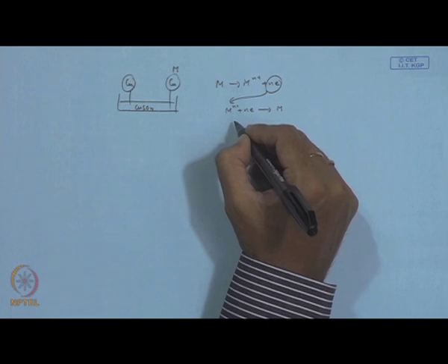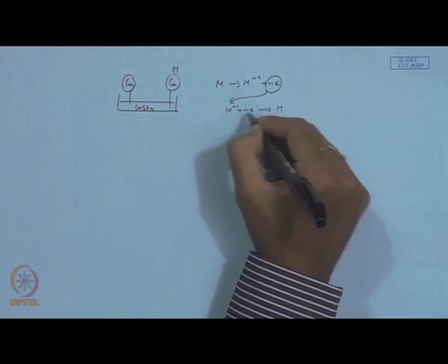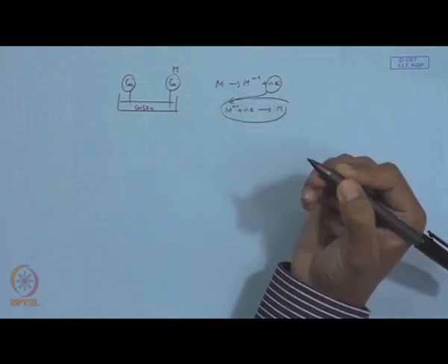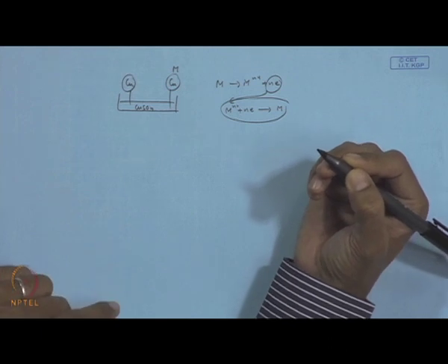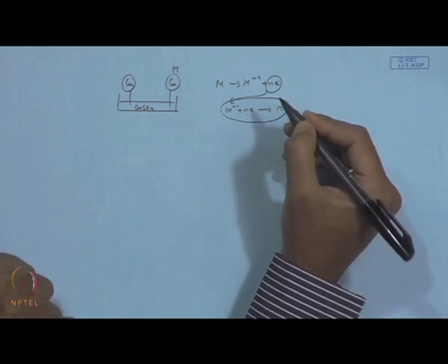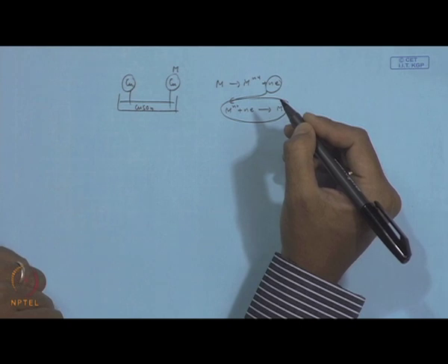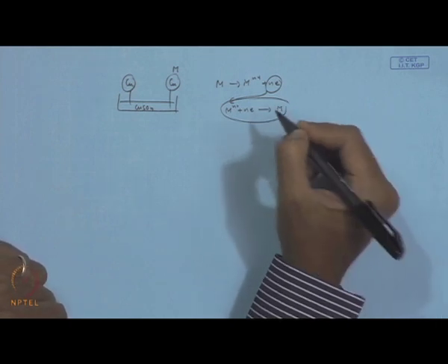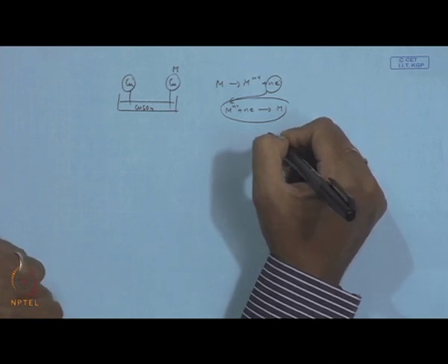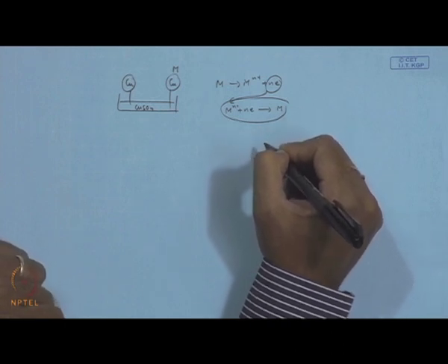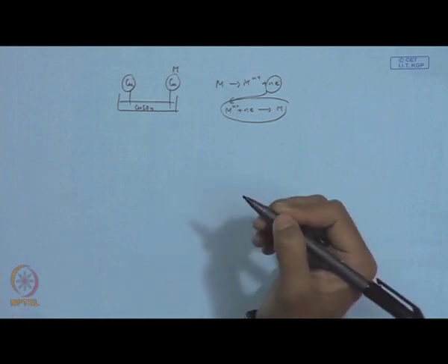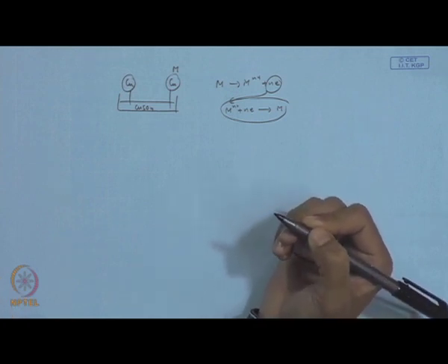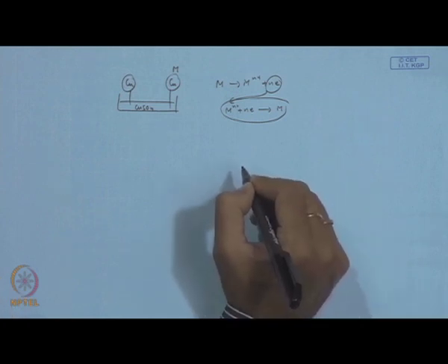This leads to secondary reactions between products of the oxidation and reduction half cells to form stable material. So if secondary reactions are taking place giving rise to stable products, then these can further react with the environment to form stable compounds such as rust, and these are very difficult to get back to the original metal.